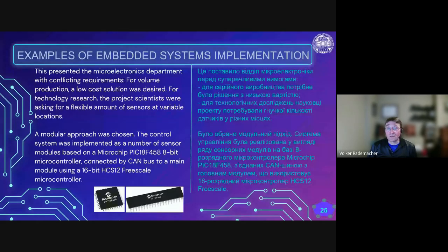So I mentioned that the PIC18F458 was one of the earliest 8-bit CAN microcontrollers. The CAN bus is originally an automotive bus. It has several advantages in this application. It is safe in terms of data integrity. The bus itself is a differential bus, and the engine that's running the CAN module has CRC protection built in.